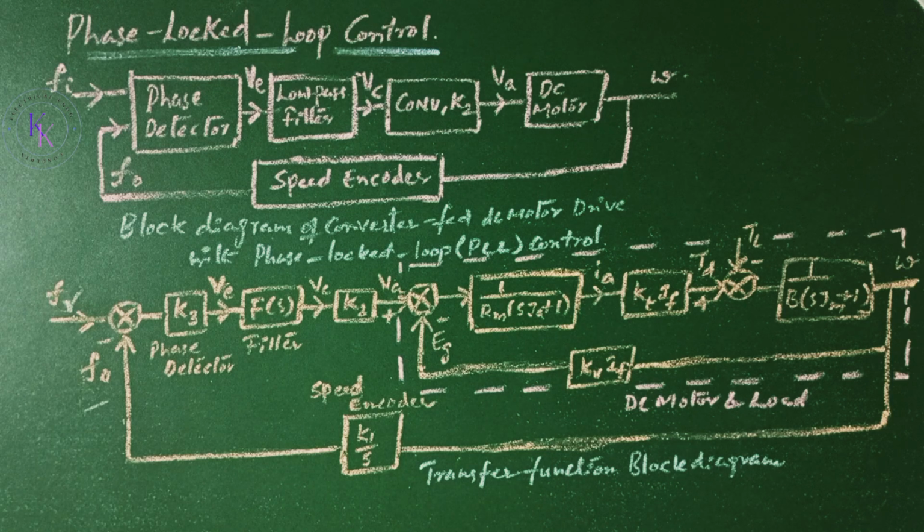The output of the phase detector would be a constant voltage proportional to the phase difference, and the steady state motor speed would be maintained at a fixed value irrespective of the load on the motor. Any disturbance contributing to the speed change would result in a phase difference, and the output of the phase detector would respond immediately to vary the speed of the motor in such a direction and magnitude as to retain the locking of the reference and the feedback frequencies. The response of the phase detector is very fast. As long as the two frequencies are locked, the speed regulation should ideally be zero.